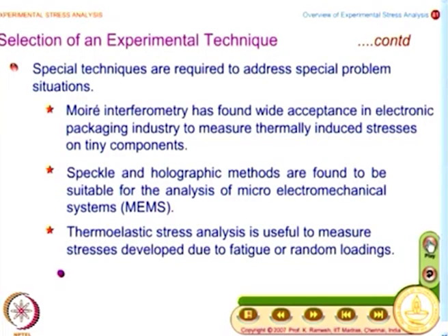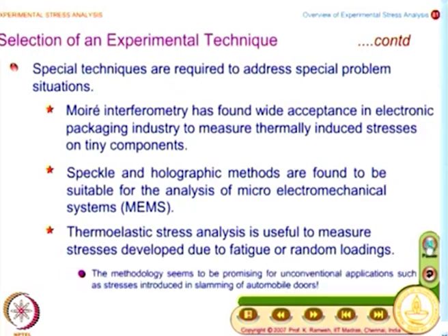Then you have the method of thermoelastic stress analysis, and this is useful to measure stresses developed due to fatigue or random loadings, and that is a very special application. The methodology seems to be promising for unconventional applications such as stresses induced in slamming of automobile doors.